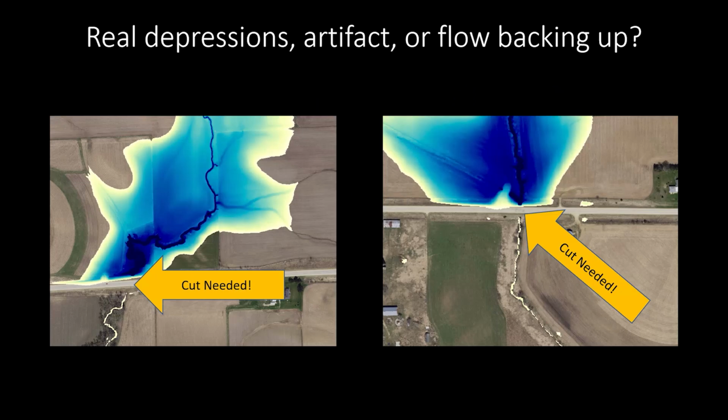The first step in this iterative process is to identify impeded flows. This tool produces a valuable output showing surface depressions across the landscape. Some of these depressions are going to be real and some are not. In the example shown, depressions are commonly developed behind roadways, meaning that flow will be backed up behind these. In reality, these roadways could actually be bridges or have culverts going underneath them or have ditches that would actually direct the flow under or around them. These areas will need to be edited to allow this flow to move correctly.